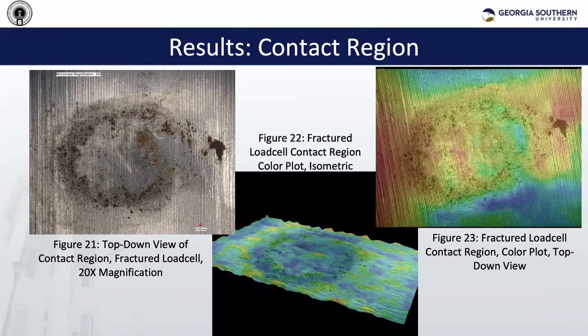Finally, the scan of the contact region between the bracket and the load cell is shown. The key takeaway that can be seen from the colored depth scans is that there are many bumps and areas of obvious dynamic contact. This indicates the pressure vessel is actually showing instability due to the dynamic wind loading, and the instability is being translated onto the load cell in the form of low magnitude impacts, which are infrequent and random and contribute to the fatigue failures found.